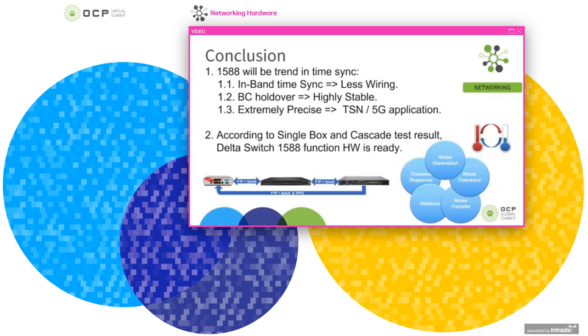So the last one is our conclusion. I think 1588 will be trending in time synchronization because it has the below advantages. The first one is 1588 is an in-band time synchronization. It means that you can use the existing wiring. You don't need a dedicated system just for timing synchronization.